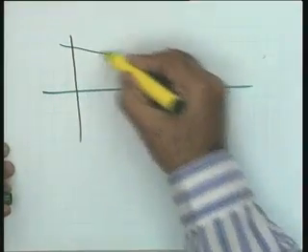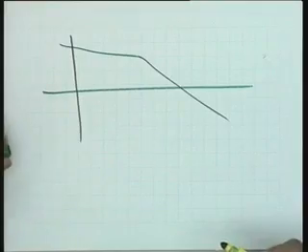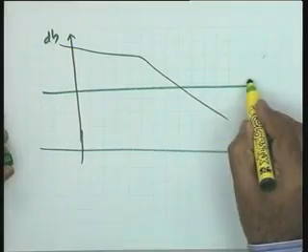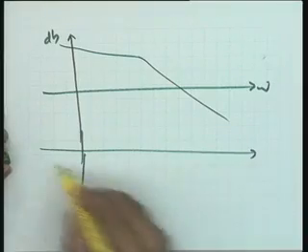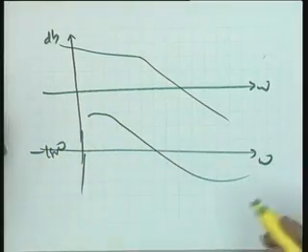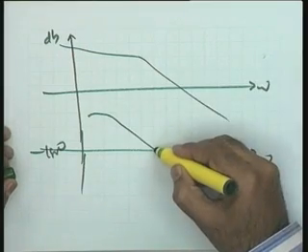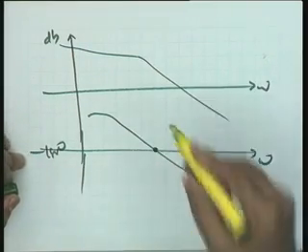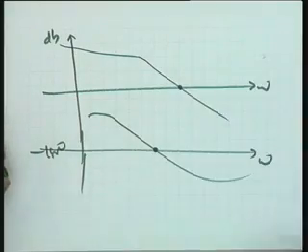Okay. Take in this concluding example on this discussion, let us say this is the system I take, and the gain dB versus omega, omega on the semi-log axis, and this is minus 180 degrees and omega. In that particular case, as you know, this is the point at which the angle is minus 180 degrees, and this is the point at which the magnitude is 1.